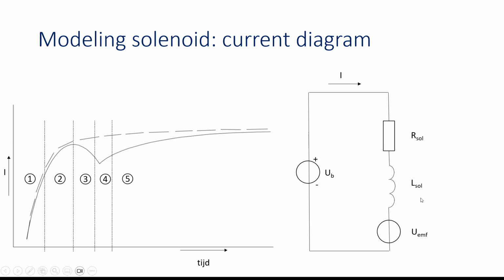It will become higher because the flux is flowing more through the iron, the permeability of iron is higher, and L depends on the magnetic permeability, so L starts to increase. So the time constant L over R also starts to increase. But also the back EMF voltage is created due to the movement of the plunger, which was in series with the R and the L.